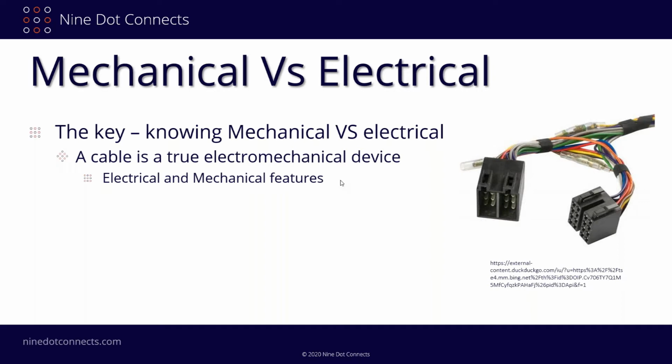So the question is, who would be best to create it? And to be perfectly honest, it really is the electrical folks, because obviously there's going to be signal integrity issues that the mechanical folks aren't going to necessarily know. Now, of course, there's other factors in it like thermal. There's going to be things like length and other things, maybe vibration. Those are things that the electrical folks may not know. So it behooves the electrical individual who's doing this to talk with the mechanical, or vice versa. But a lot of times it does fall in the hands of the electrical folks to put these together.